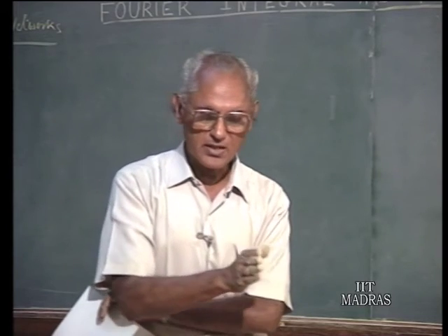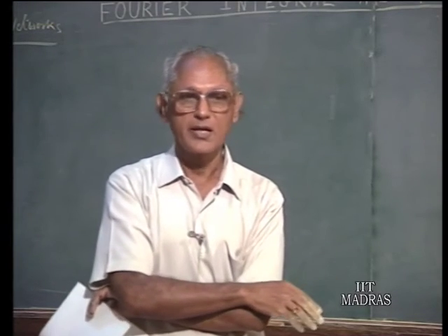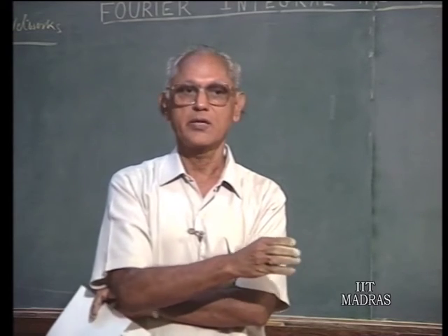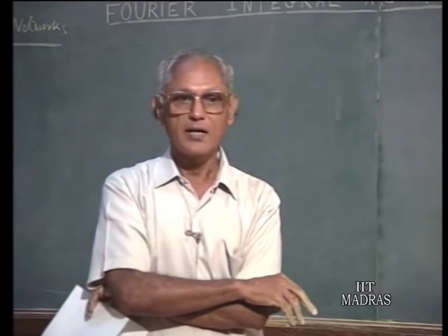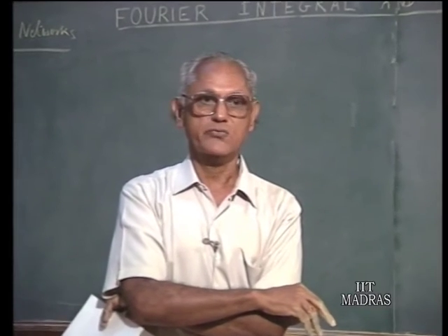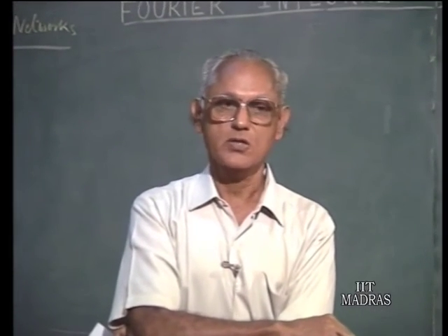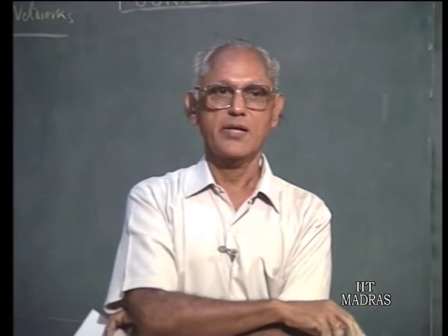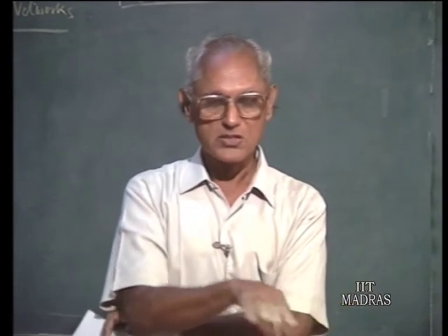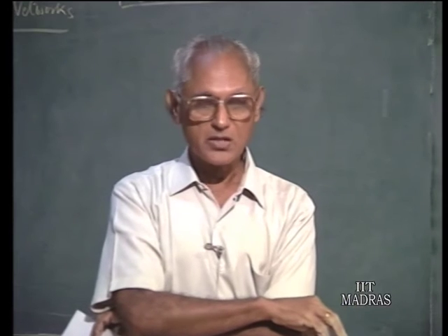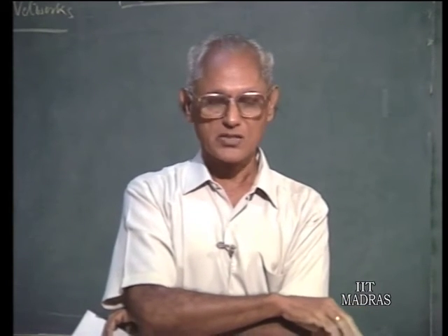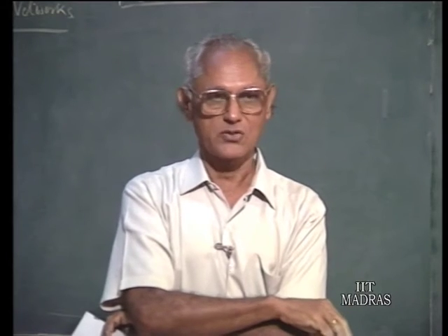That means the excitation is 0 for negative t, and we would also like the response to be 0 for negative t because it is a causal system. If you take the inverse Fourier transform of Y of j omega, it turns out that for such systems the response for negative t is 0. This is in accordance with the causality principle, and therefore there is no necessity for natural response terms to appear in the final solution.